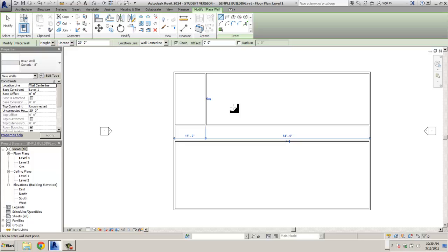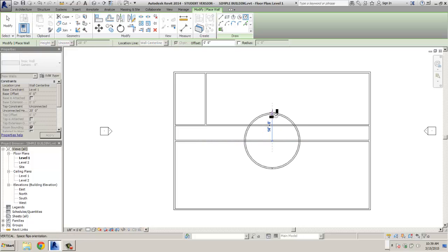The next thing we're going to do is draw on the next page, 2-23, we're going to draw a panel. We're going to select a circle. We're still in our wall tool, so we're going to select this circle tool up here. We're going to find the midpoint of our corridor wall, and we're going to draw a 16-foot diameter, or excuse me, 14-foot radius circle. So come down to 14 feet, left click, and that's it.